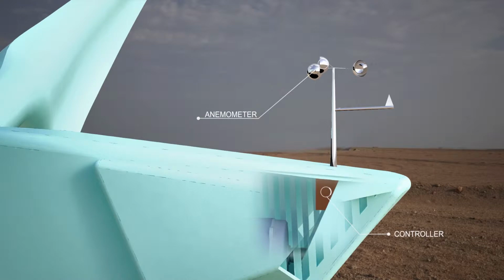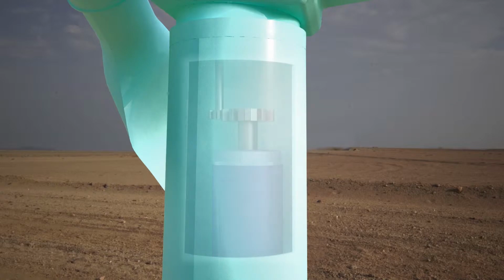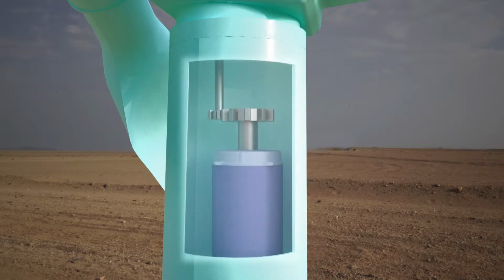Turbines do not operate at wind speeds above about 55 miles per hour because they may be damaged by the high winds. Wind vane: measures wind direction and communicates with the yaw drive to orient the turbine properly with respect to the wind. Yaw drive: orients upwind turbines to keep them facing the wind when the direction changes. Downwind turbines don't require a yaw drive because the wind manually blows the rotor away from it. Yaw motor: powers the yaw drive.